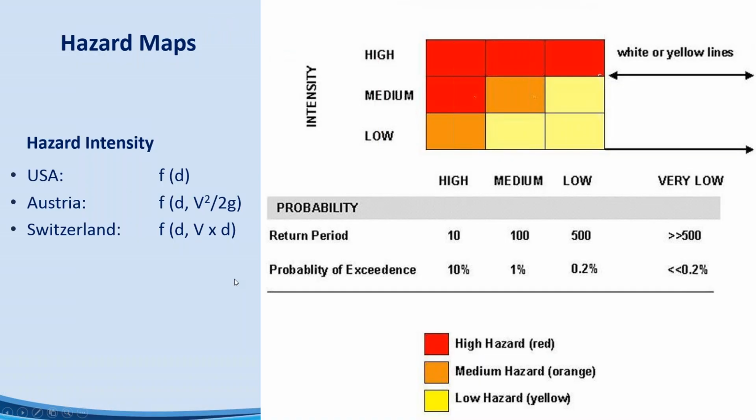So what these hazard maps do is they are combining and interpolating between high hazard events and frequency. When you have a very high hazard 500-year event, it occurs with a fairly low frequency. So it may pose a less hazardous scenario than having a lower intensity hazard based on the 10-year event, but a more frequent occurrence of the hazard.